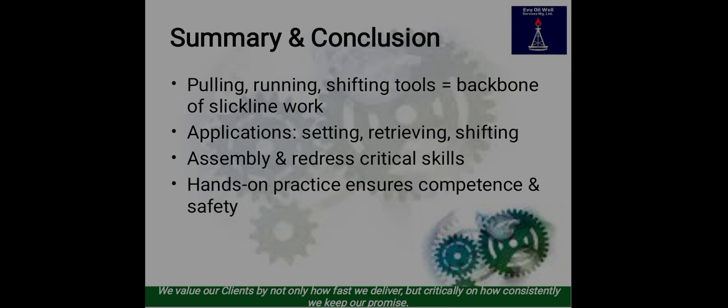Implement a stop and verify protocol when tool behavior is suspicious. Train crews regularly on mechanical shifting principles and sleeve identification. Keep digital logs of tool redress and maintenance history.